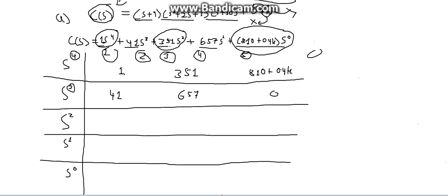Now the introduction and creation of the table that we can then begin analyzing is complete. To begin the analysis of Routh's criterion, you start off the initial term for your third row down. Mind you, it's 3 values, always 3 irregardless. Just remember that, guys. That actually does depend on your order of polynomial. If you have s to the power of 6, then you can have 5 columns, and that's when it gets a bit tricky and you might have to use your graphics calculator.